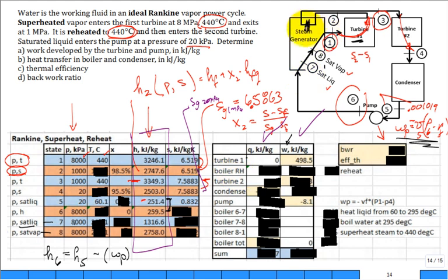This section right here, what goes into the working fluid in that reheat section. There's no work. And 601.7. How did you get the 601.7? Isn't that H3 minus H2? Yeah. All right. Turbine, second turbine. You didn't fool me. 0 on the Q. And then 846. How do you get this 846? H3 minus H4 for the second turbine.